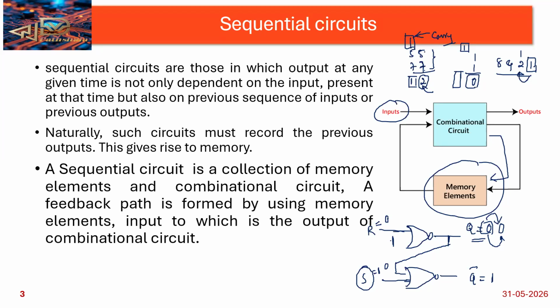I just wanted to ask why the ripple carry adder is not considered a sequential circuit, because in it also part of the output we are adding to the next. Part of the output, yes, but there is no storing element in that. We are just forwarding the value.